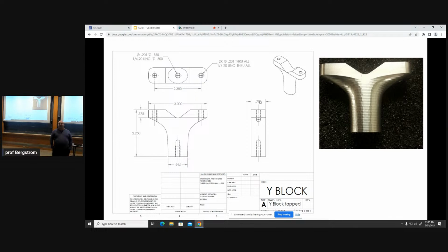So within 10 thousandths of an inch, I don't care. That's what the tolerance means. Why did I decide that? Because with a small tolerance like that, you'll still be able to have varying parts. You'll never be off by a big difference. So tolerances allow us to not make the part exactly correct.